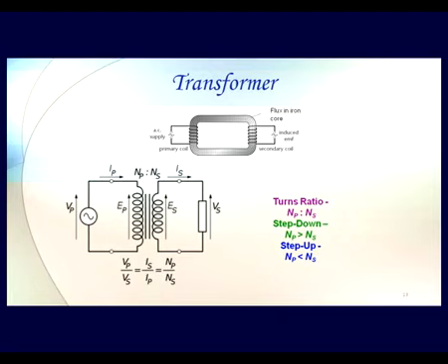Now if we have primary turns lesser than secondary turns, then it is going to induce a higher voltage in the secondary than the mains input voltage, and that's why it is called a step up transformer. That is also quite commonly used, like if we have, say, electron guns in our television circuit, the old kind of television circuits where we used to have a cathode ray tube.